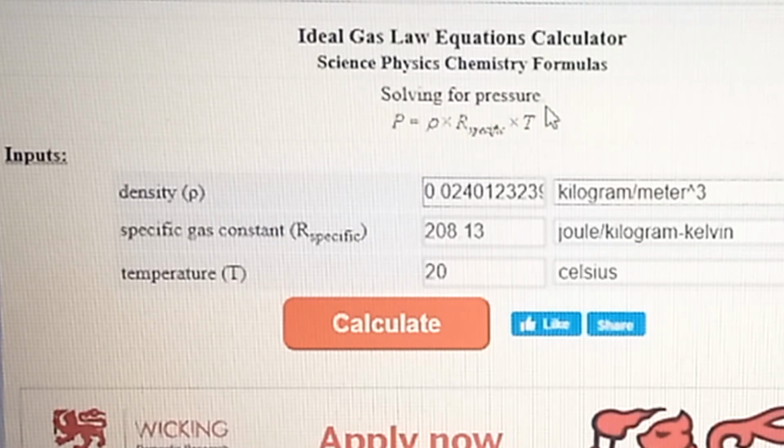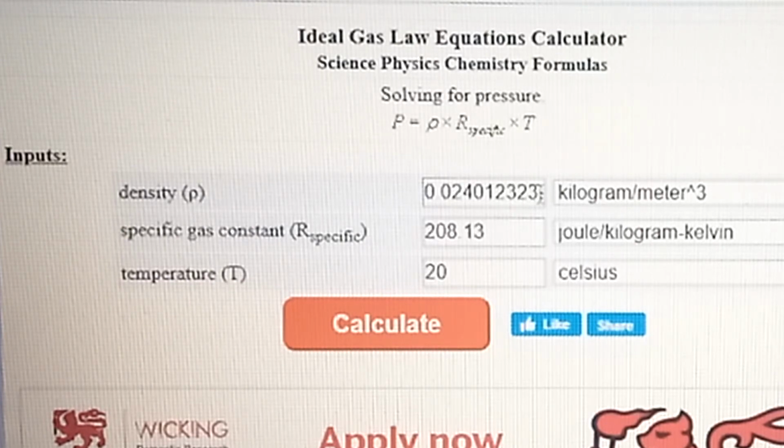We're trying to solve for pressure, because pressure is how you physically adjust or measure the vacuum inside of the vacuum chamber. That is what the gauge will tell you, and that is why we need to punch all of these inputs in to solve for pressure.